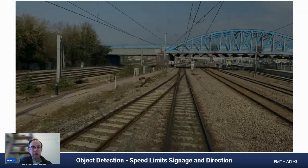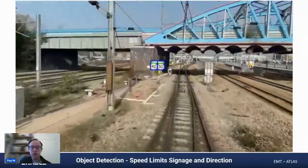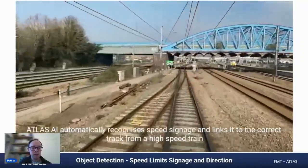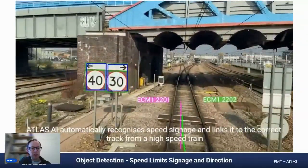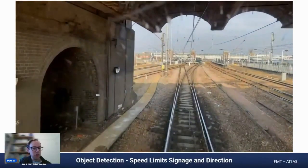In another specific example, we have the capture of speed limit signage along the rail corridor, further enhancing its capture by using additional techniques to automatically identify the limits being displayed. On top of this, we can also identify the specific track each limit is associated with. Here we can see a pair of speed limit signs being identified, and OCR being used to detect the limit values displayed. And then to identify the associated track routes, we can fuse this with our track vision data, a topic we'll cover shortly.